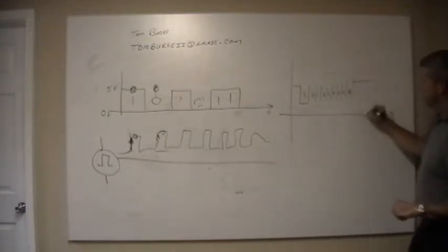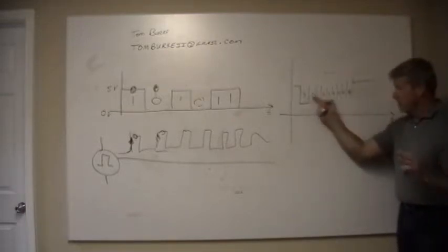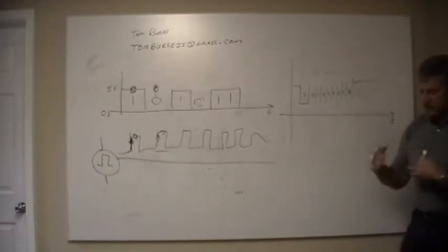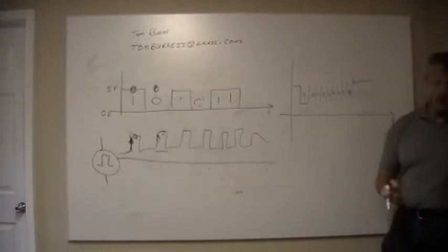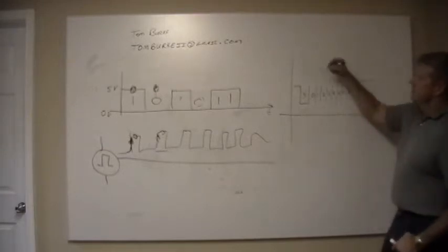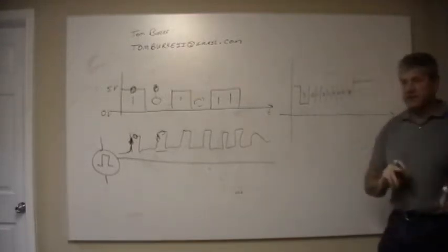And all this stop bit is for is to give it time so that the system knows, oh, those bits there were together. And so inside you run a clock and you say, oh, I'm running at 4800 baud or 9600 baud or whatever the baud rate is. The baud rate is slightly different than the bit rate.